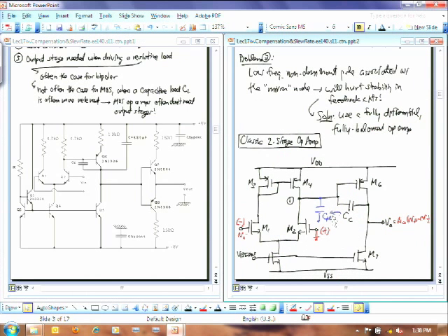And so what you're trying to do with this C sub C is put that pole frequency, the first pole frequency, in a slot where it's significantly distant from the second pole. Okay? Now, it turns out that in this op-amp, this capacitor is also doing that same function. Okay, so that's what this 680 picofarads is for.